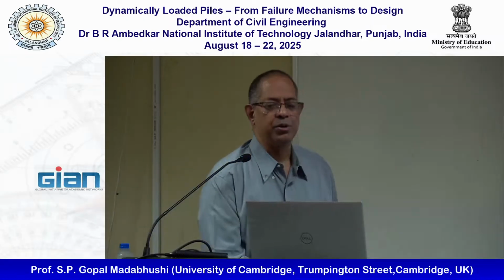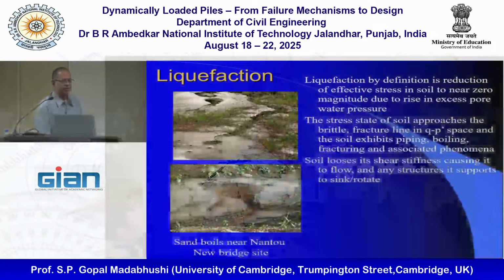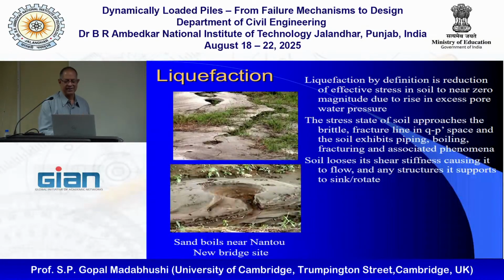Typically, this is a good problem to look at liquefaction of ground. We talked about this yesterday already, so I'm not going to go into the details. Basically, what we are saying is the soil will lose its effective stress almost to zero as the excess pore pressures build up. And the excess pore pressures build up because you're trying to shake the soil. It wants to change its volume, but there's no time for the water within the soil to escape. You can actually show this in the q-p' plane. I don't know if you use this framework.